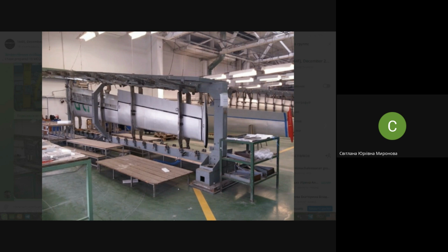And in such an assembly jig, we start work with transversal elements, like locating the ribs, locating the frames, rims, whatsoever. Next we locate stringers, and next we cover everything with skins. More probably it was a jig for locating by elements of the airframe. When we're looking at the structure of a jig, we need to understand what assembly methods are more probably in use. Considering how many locators they have in those jigs, as I already said, it comes to a jig by airframe locator.